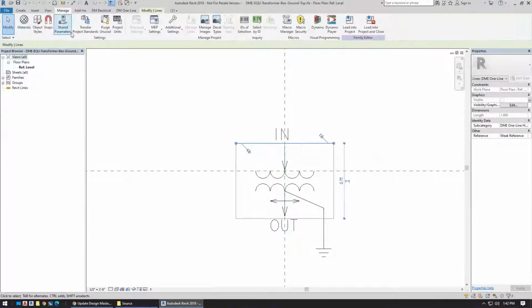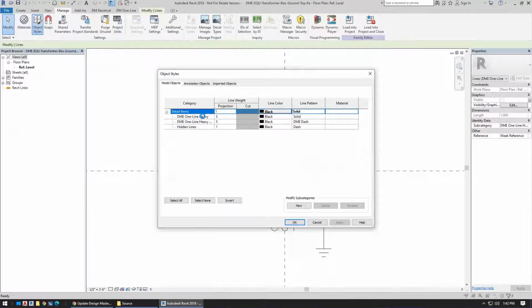By default, we have some styles: heavy, solid, and dashed for all of our items, with heavy, medium, and light line types. So that when all of our stuff comes in, it'll use these line types, and then you can set them in your project to what the line weight should be, because everyone has their line weight set up a little bit differently.